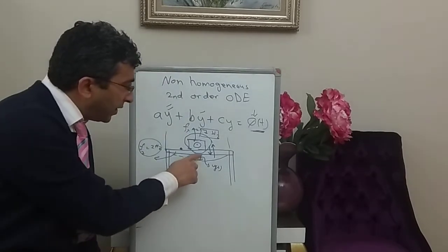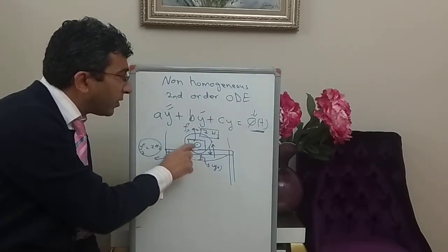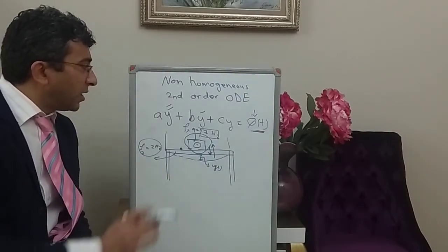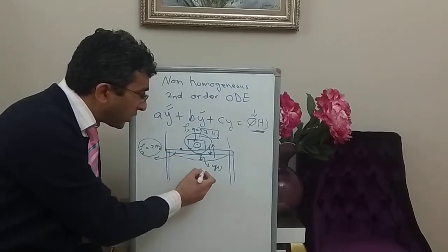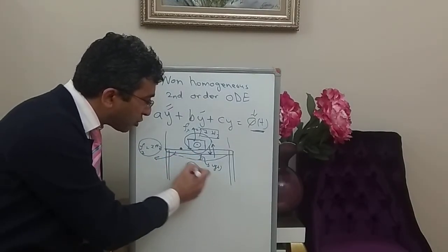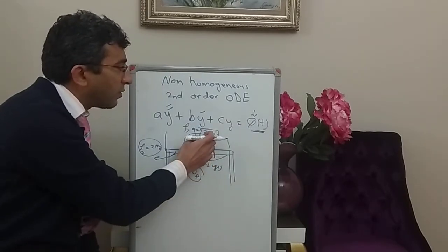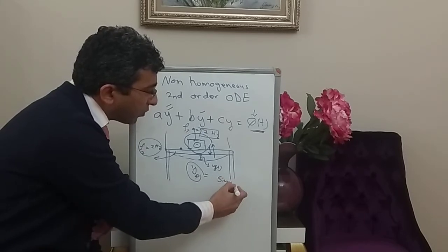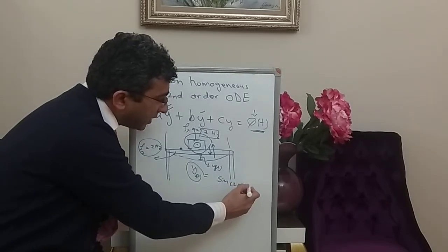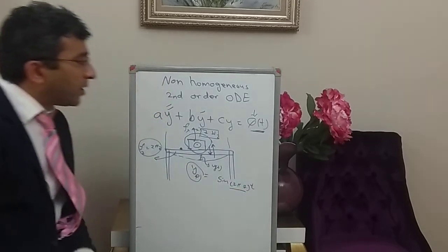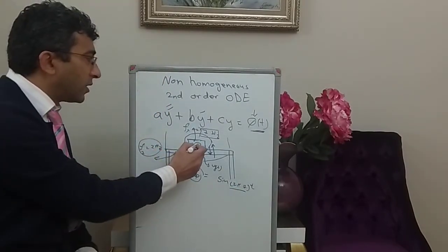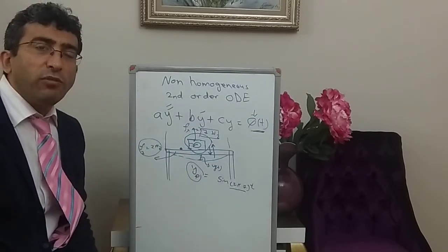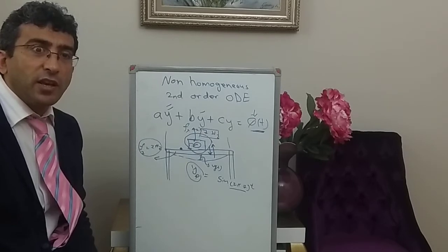However, the amplitude of this vibration is not the same as the amplitude of the exciting force, as you will see. So this is important: the particular solution part depends on the characteristics of this. In the particular solution you will have a sinusoidal function that works with 2 pi f, where f is 7 Hertz here, times t. So if this is a sinusoidal excitation, the slab will vibrate with the same frequency as the exciting force.